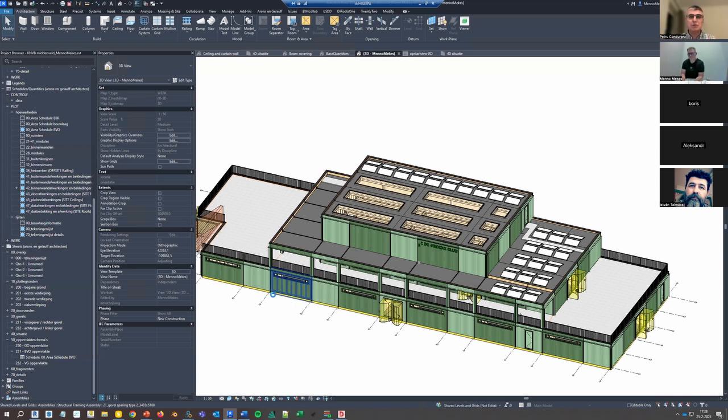So we have attributes, we have quantity sets, we have classification systems, we have materials, all these things. We have IFC classes themselves. The first thing we have is types. We have to use these things first, and only after that, what remains and we cannot fit anywhere else, we can put together. I understand also the justification.